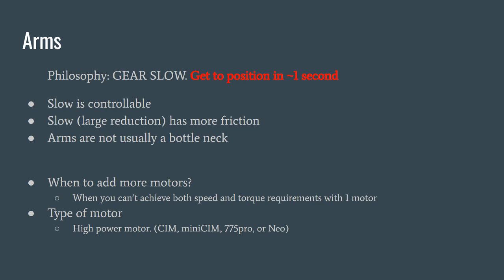Neos are brushless motors, so I'm not going to explain the details of a brushless motor, but I don't really understand brushless motors that well. But the Neo's behavior is more powerful than a Sim, and it's like somewhere between a 775 Pro and a Sim for how robust it is. So you really don't want to stall it for that long, but it's pretty good actually. So Neos are awesome actually.